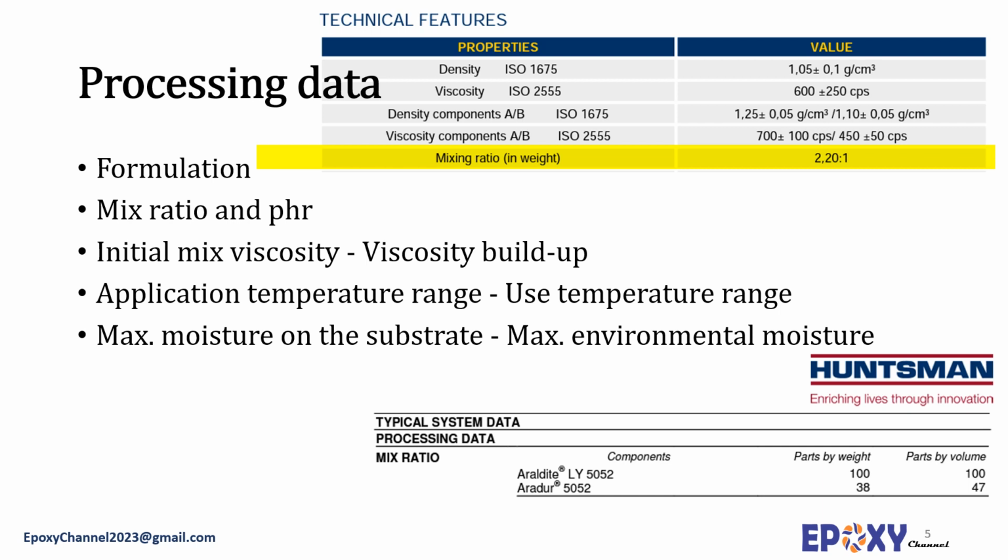We have also another term known as PHR, which stands for per 100 resin. This indicates the amount of the certain components in 100 grams of the final formulation. Therefore, a mix ratio of 70 PHR means that simply 70 grams of component A has to be mixed with 30 grams of component B. Let's emphasize again that PHR is based on weight and can be presented by the supplier or simply calculated based on the EEW of the resin and the amine weight of the hardener.